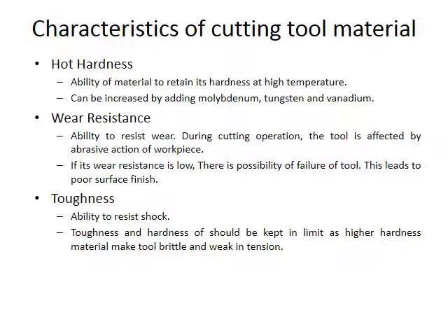The second important property is wear resistance: the ability to resist wear during the cutting operation, as the tool is affected by the abrasive action of the workpiece. If wear resistance is low, there is a possibility of tool failure. This leads to poor surface finish. This is a very important drawback.